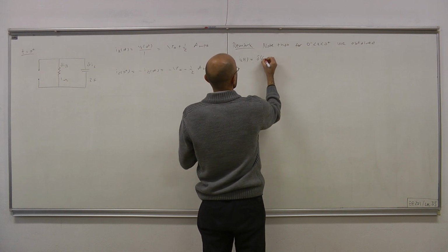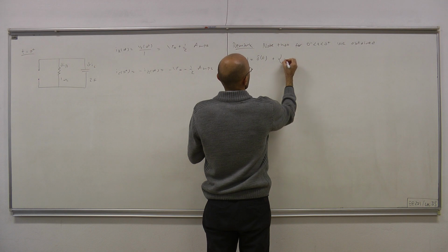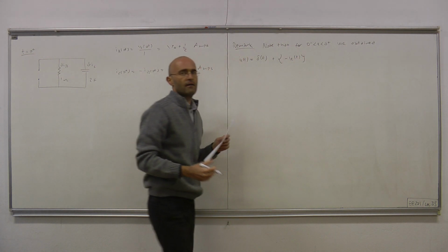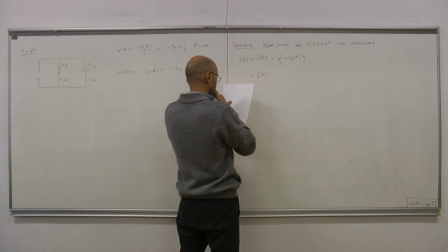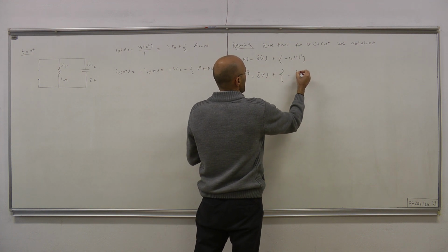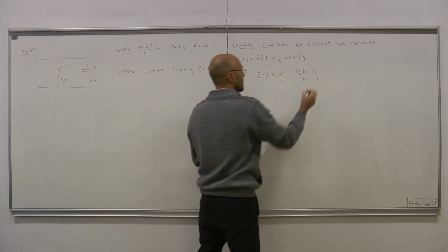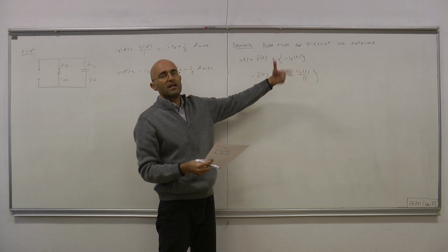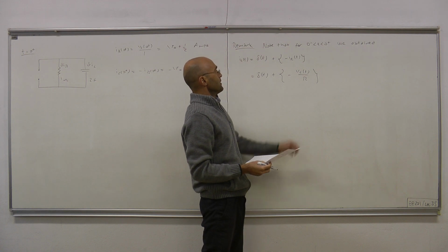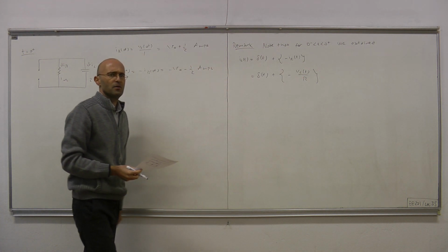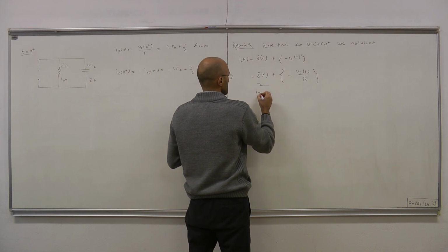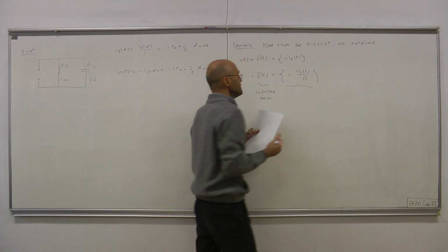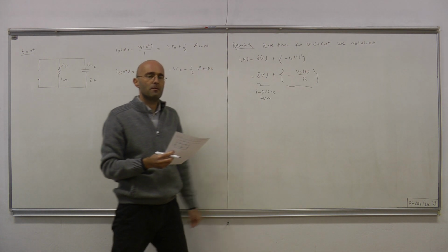iC(t) equals δ(t) minus iR(t). So that was by KCL, and that we can write as δ(t) minus vC(t) over R, because vC equals vR, and then we can transform current to voltage, the capacitor voltage, as such. Now this is the impulsive term, and this is a bounded term because the capacitor voltage is bounded.